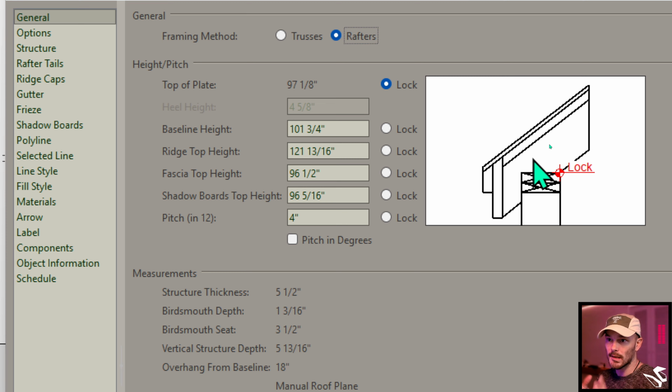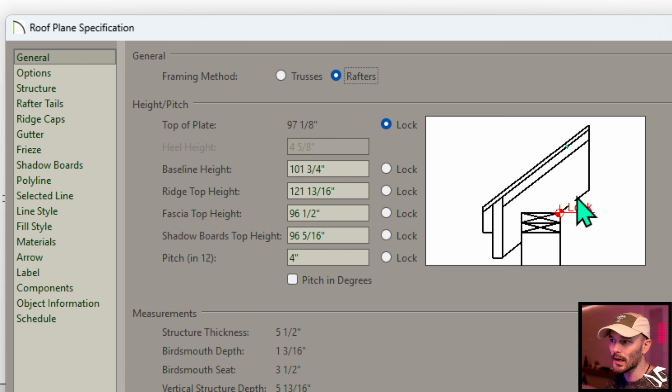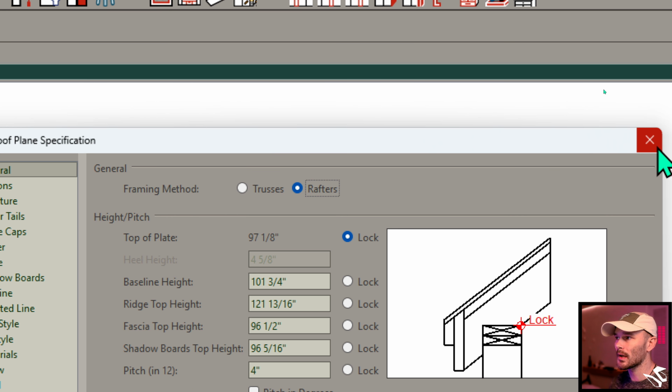You can put as many different layers as you want in that main layer, but of all those main layers, the most exterior side of the main layer is this point right here on the screen, and that is where our baseline should go for a roof where we've got a typical heel height or bird's mouth cut, what have you. This is going to be a typical roof assembly, okay? So our baseline is aligned with this exterior of that main layer.